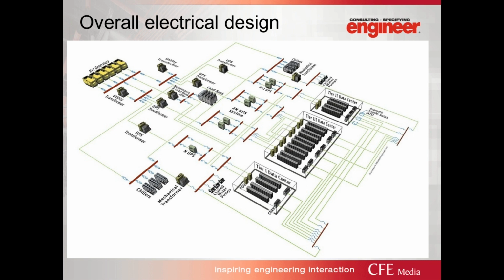Scale sort of changes the perspective of how you're going to maintain them, what that cost is, and what that schedule looks like. Oftentimes we'll find consolidated systems with a key interlock piece of switchgear that could connect to any generator easily. That could also be used as a redundant bypass means around UPS systems down to the critical load when you're maintaining those. There's a lot of sophistication and a lot of opportunity that goes into the ways in which you can efficiently deploy means to maintain and test your generators.